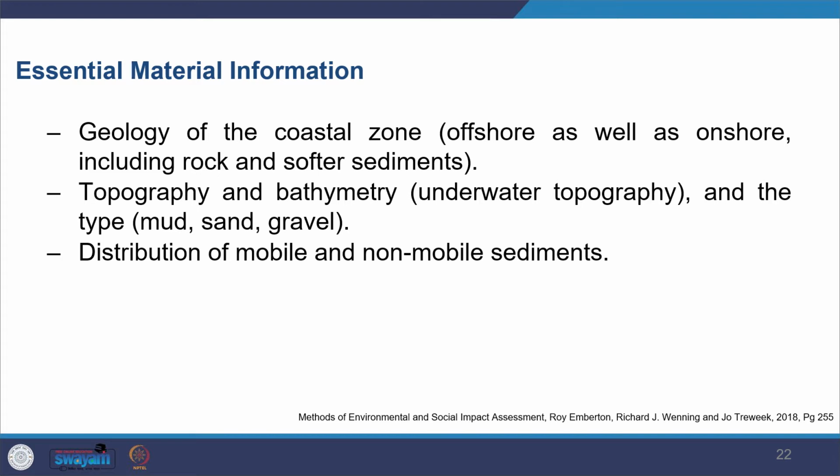And the important material information which you require for EIA purposes is the geology of the coastal zone. You look at how the geology is offshore, what the geology is onshore, how the rock is, how the sediment is, softer sediments, and so on. You look at the topography, the profile of the land, what all is there and what the shape profile of that land is. And then you look at the underwater topography, which is also called bathymetry.